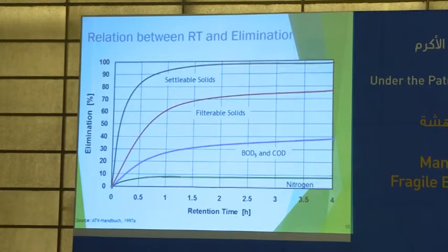What is the effect of retention time? You can see in this figure how the retention time affects the elimination of the solids. But at a certain time, it is not efficient to increase the retention time because you will achieve most of the target you want from it. So at a certain point, you have to stop increasing the retention time because it's a waste of energy, and you cannot get a higher elimination percentage of the solids.